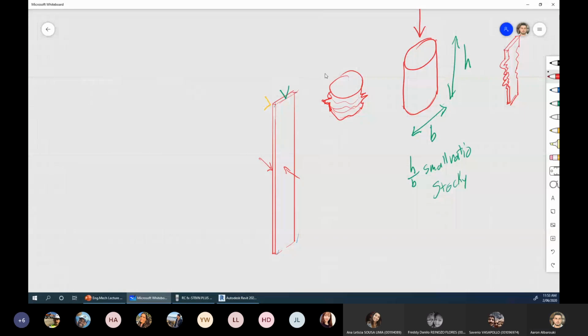kilograms? So if I tell Saverio, can you please just hold it in the center? Don't allow this ruler to buckle to the outside. So if Saverio would do that properly, that means there's a chance I can load here 10 kilograms before this ruler will start buckling to the side. So let's put everything together now and try to understand what happens.